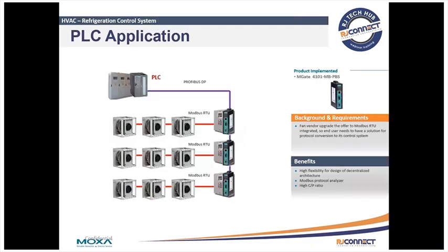Another application was a PLC application where the existing system had a Profibus PLC using Profibus DP, but they needed to communicate with Modbus RTU slaves. So the fan vendor had an upgrade to offer to Modbus RTU integrated, so the end user needed a solution for protocol conversion for its existing control system. The benefits for this customer were the high flexibility for design using the decentralized architecture and the Modbus protocol analyzer, and also a high cost to performance ratio.